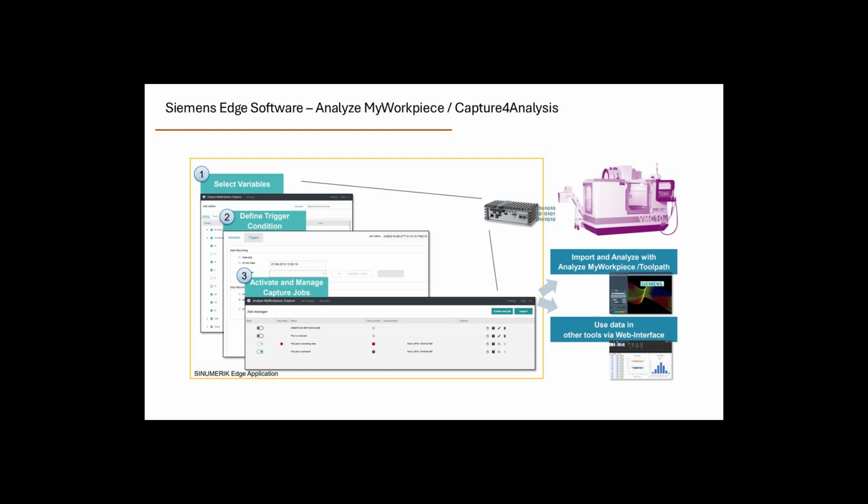So what the Edge device gives us the capability of doing is actually defining triggers. And the way we define the triggers is in Siemens NX CAM. When we generate the tool paths, for each tool path, we have a start and end condition. And to the start and end condition, we can add a trigger phrase. Once you post out that program, that trigger phrase shows up in the G code as a commented line. You can have it be whatever you want it to be.